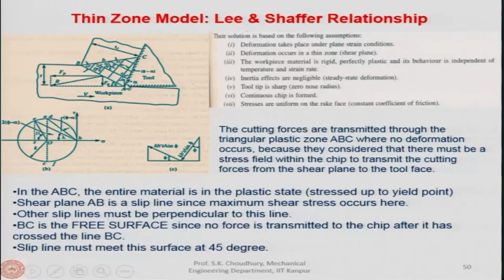During the machining process, the shear plane angle phi changes itself in such a way that power consumption remains minimum. In Lee and Shaffer, the principle is very different. Here the principle they are using is the slip line field theory. Okay. Now, we are not going to discuss the slip line field theory in detail, but we will be using the concepts only, all right. Let us see in this slide.